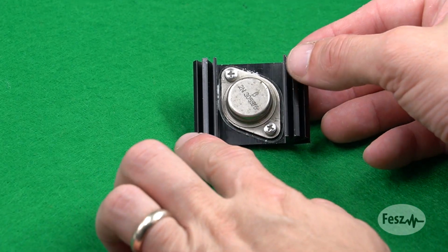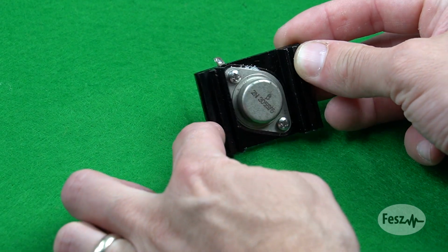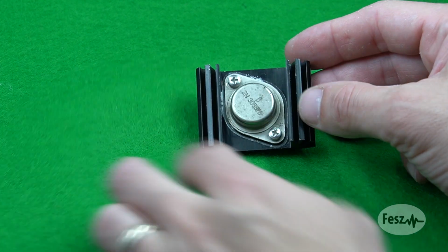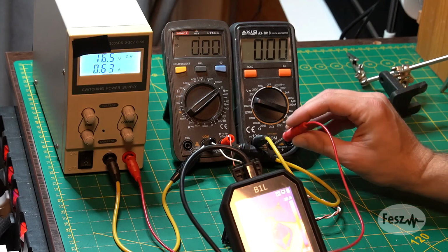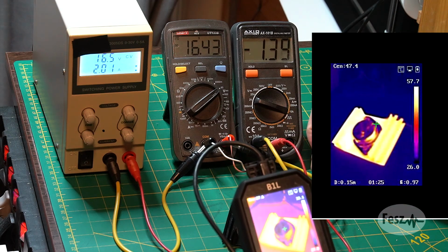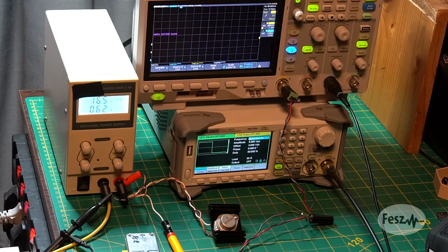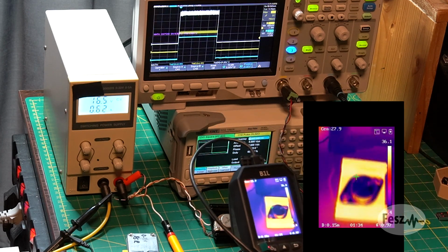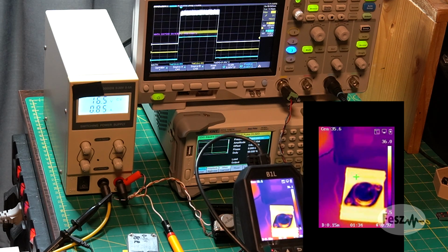So to illustrate this, what I have here is an old 2N3055 transistor stuck to a small heatsink. The combined thermal resistance from junction to ambient of the complete system is about 10 Kelvin per watt. So if I continuously dissipate 30 watts into this, the temperature of the junction would reach 300 degrees Celsius above ambient, which would clearly destroy the transistor. However, if I apply some specific pulses to it, nothing really happens. If the pulses are short, on the outside at least, there is barely an increase in temperature.